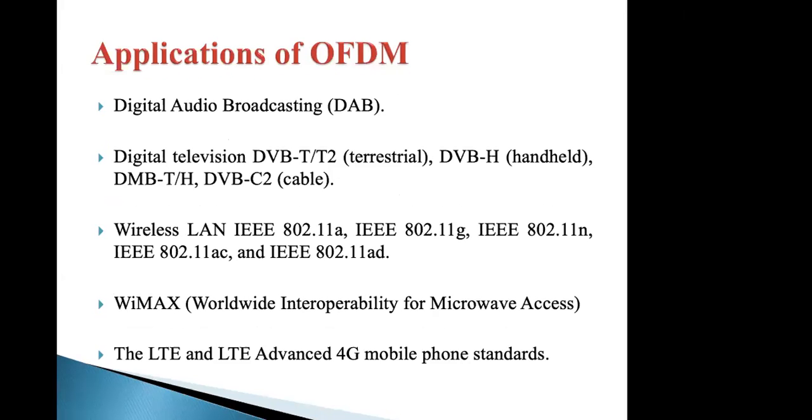Currently we are using OFDM in LTE, LTE Advanced, DVB-T2 terrestrial telecommunication, as well as 802.11a, 802.11g, 11n, 11ac, 11ad. In all these wireless standards we are using OFDM. Also in WiMAX, that is Worldwide Interoperability for Microwave Access, LTE Advanced and 4G mobile phone standards, we are using the OFDM transmission scheme.